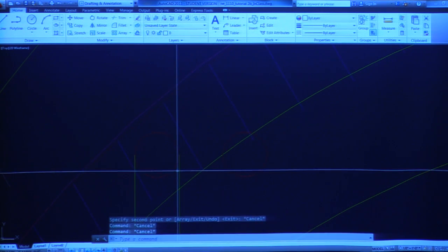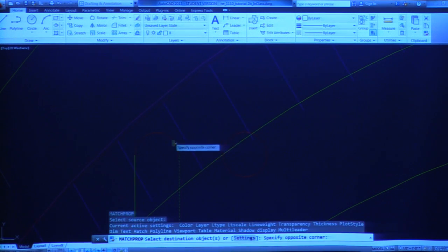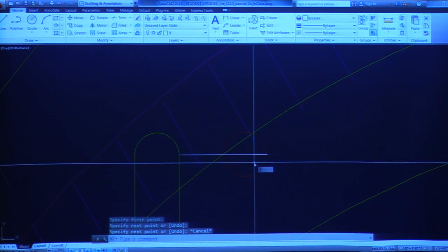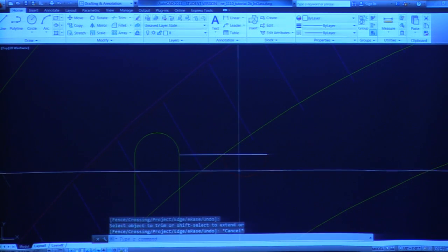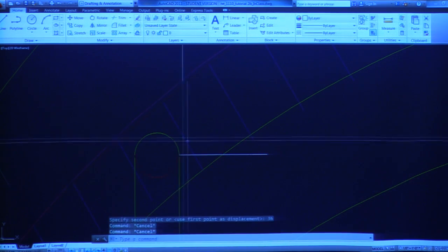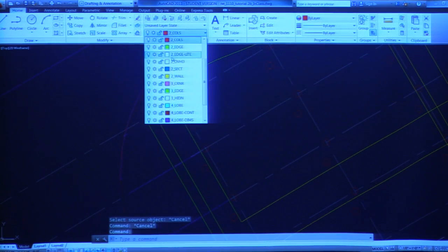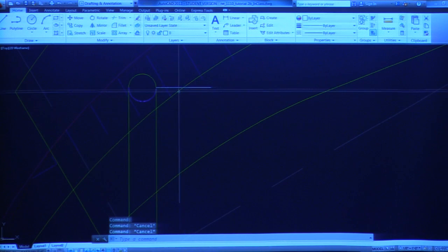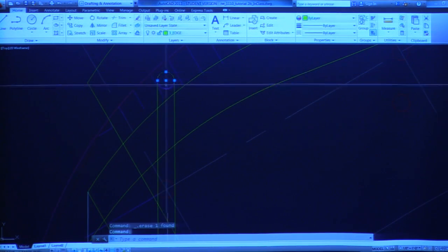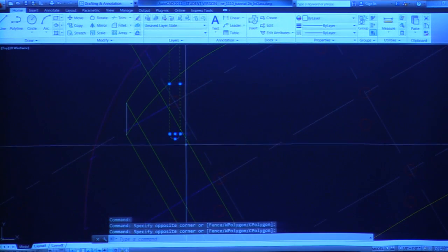So what I'm going to do here is trim this out so I can now match properties with that. And then, I mean, this is maybe a slow way to do this, but then I trim here, move this back 36, and then I make this the 3 corner. So it's like the cube. And now this is a good 3D column that I can copy around in place.